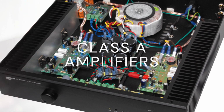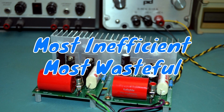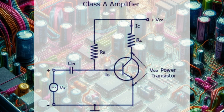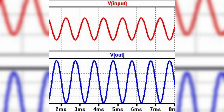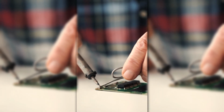Class A amplifiers are the simplest and most linear, but also the most inefficient and wasteful. In a Class A amplifier, the transistor is biased in the middle of its active region so that it conducts for the entire cycle of the input signal. This means that the output signal is an exact replica of the input signal, but amplified. However, this also means that the transistor is always on and dissipates a lot of heat and power.